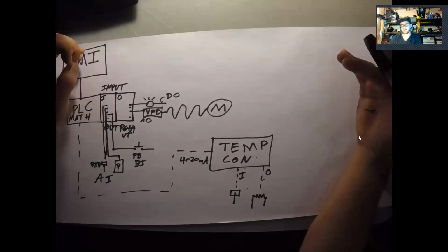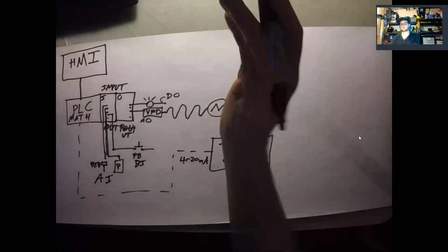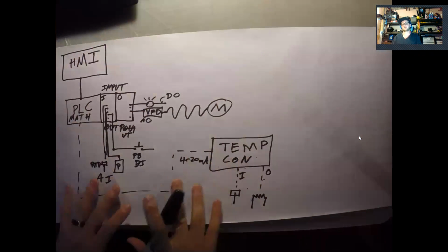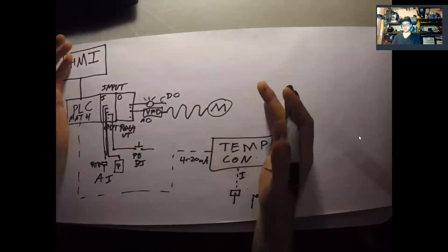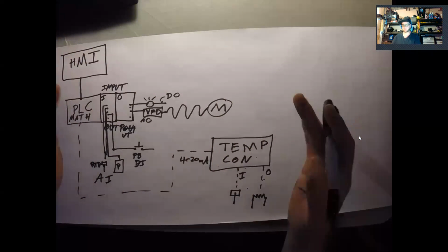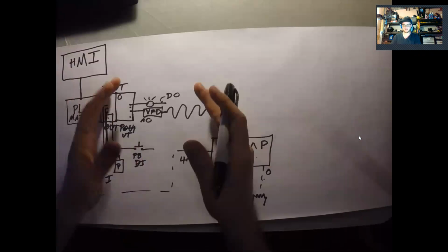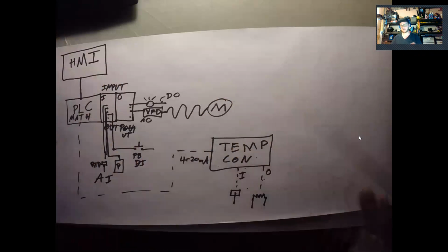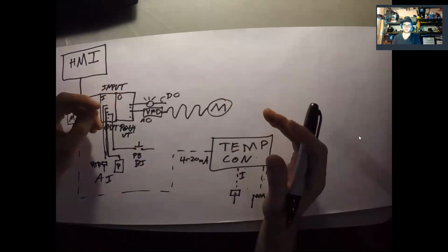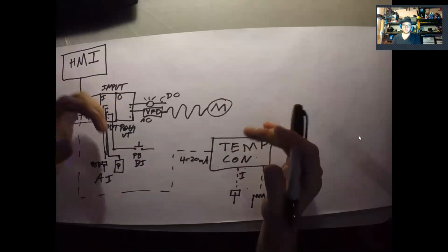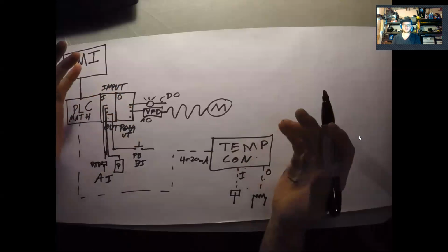And so you'll buy a specific specialized system from a vendor that's a skid-based system. And what that means is it's just on a metal frame that they built at their warehouse, and they ship to you, and you bring it in and you set it down and you connect some process piping to it, and then it's ready to go, and it just works from the factory.